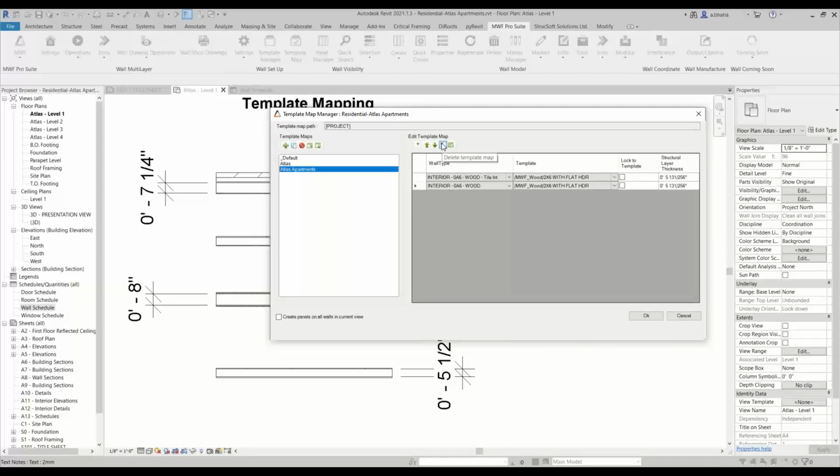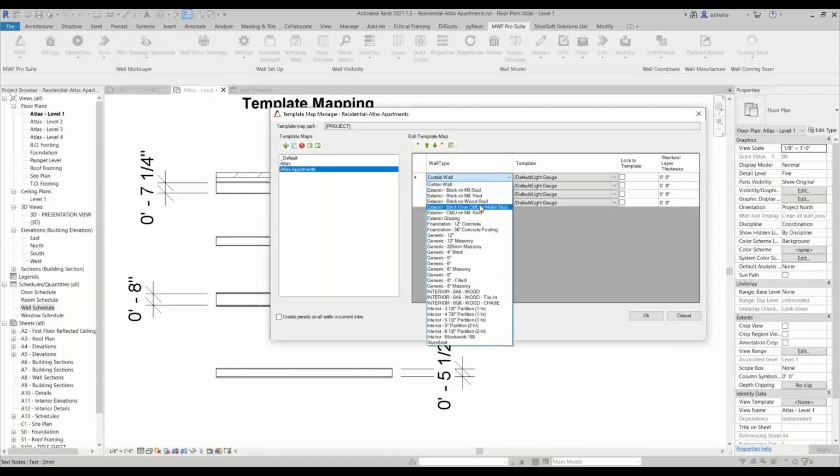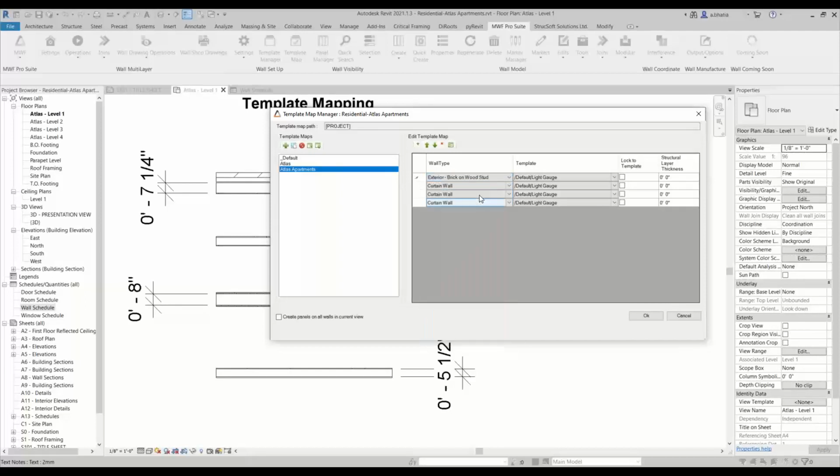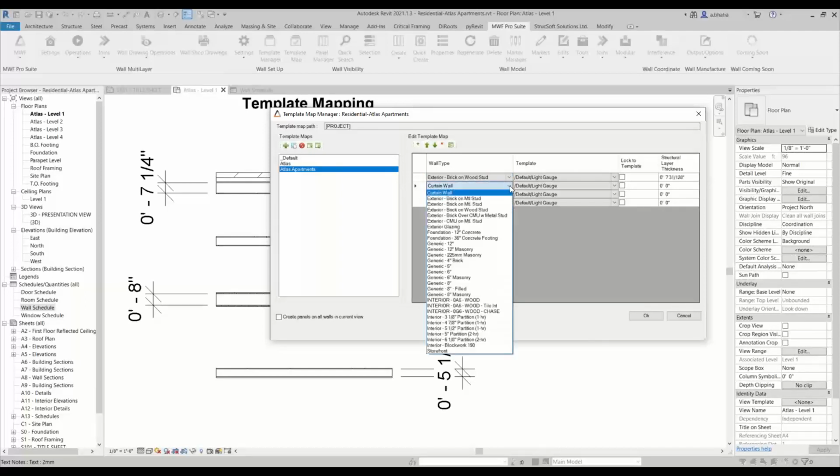So for us, what I will do is I'll manually create all of our templates, okay? We have 4 walls here, so I drew out the 4 walls that I saw in my schedule. I'm just going to add those 1, 2, 3, 4 walls here. And then I'm going to select the walls that I know need to be framed. So that's the wood stud wall here.